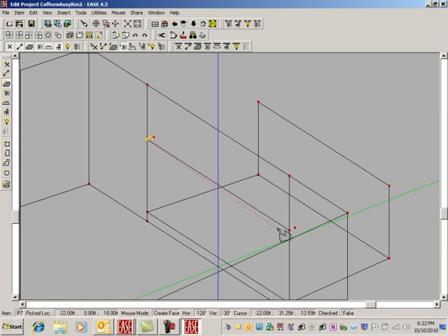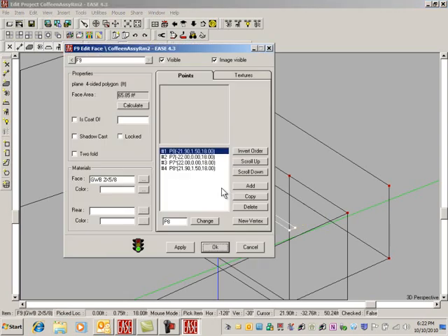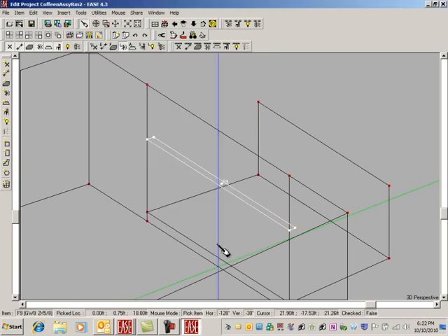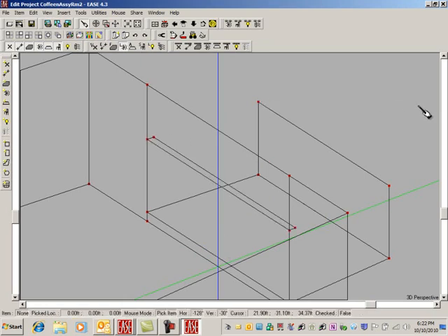So let's do that again. 2 divided by 21, 0.09, and the inverse sine of that. That's up about 5.5 degrees. So our vertical angle is 5.5 degrees.